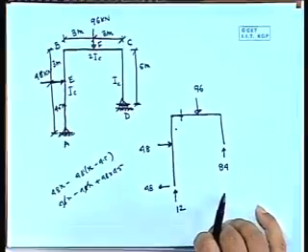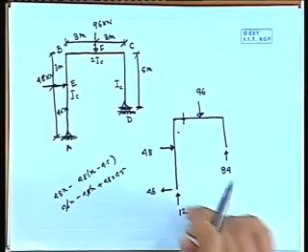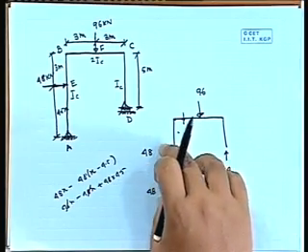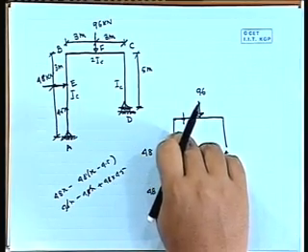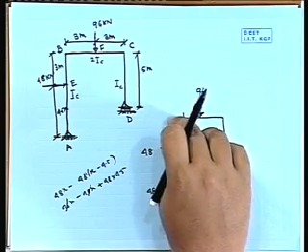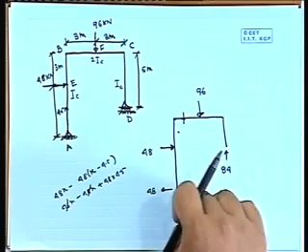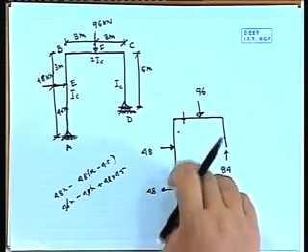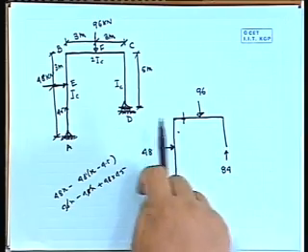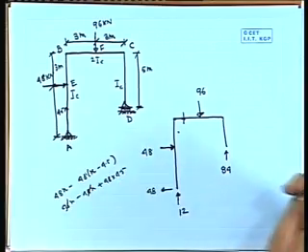So this part you try to follow. Here this 48 and 48 will generate a moment. That moment will be carried throughout constant, and here to here it is connected. The moment will be transferred. Now 12 was not creating any problem because it was on that line. Now once we move horizontally, 12 into x will be the additional moment.